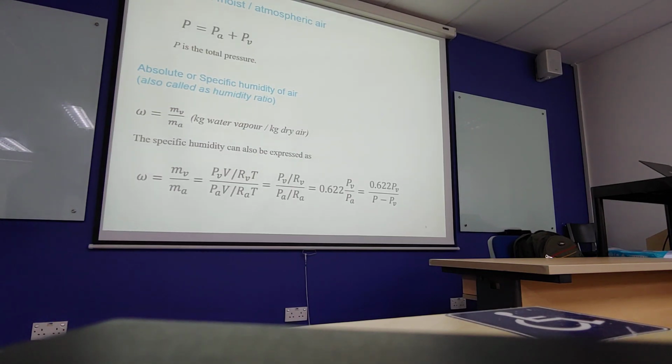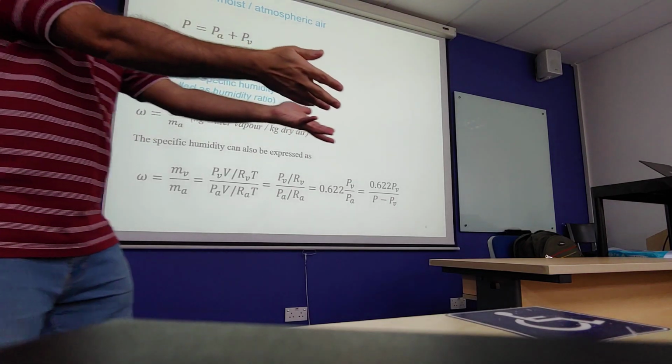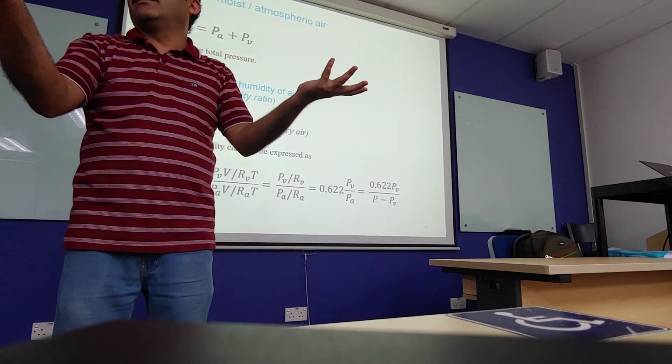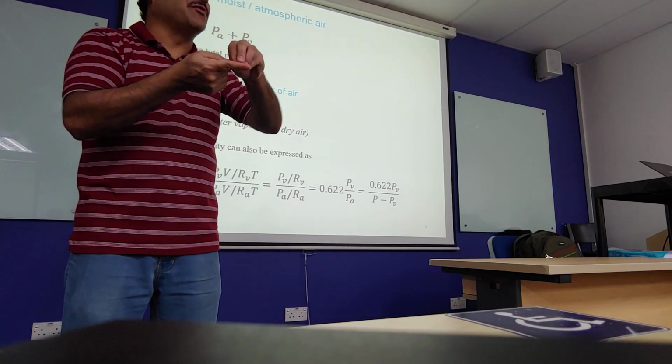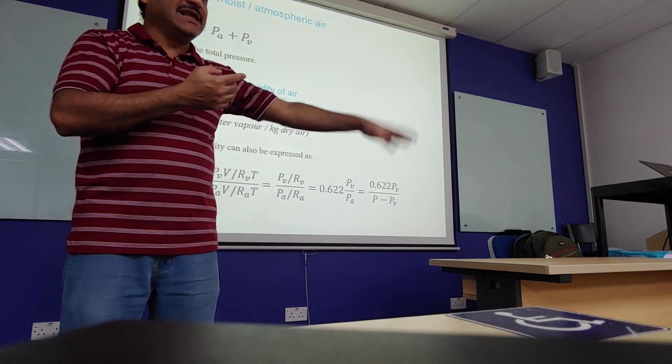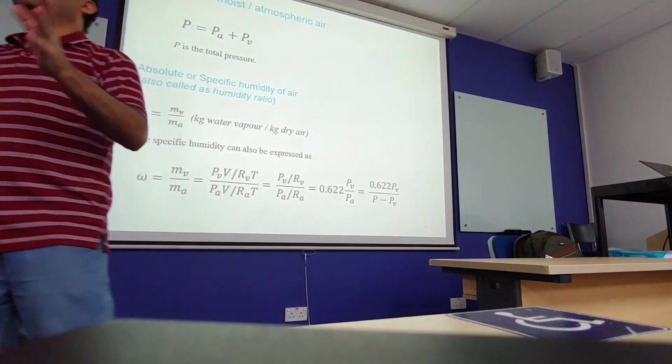Now, can you visualize a thermometer, how it looks? There's a glass tube, and there's a small bulb at the bottom which has some kind of fluid. Sometimes mercury, which is banned these days because of toxicity, maybe alcohol. So some kind of red or green fluid inside which goes up and down depending upon the temperature. That bulb, when we leave it anywhere, is exposed to air, and on the surface it's dry. Basically, there's no water on top of it. So if we just leave a thermometer on the bench, it will read dry bulb temperature.